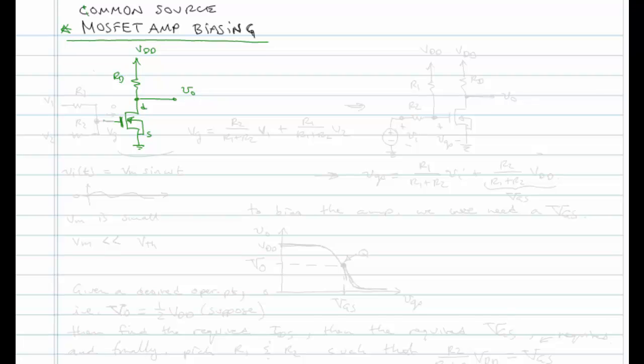So what I want to set up is a scenario where we have an input signal, ultimately an input signal that is going to be a pure AC signal, no DC offset. So let's say it has some magnitude Vm, and it's a sine omega t. Okay, so just a simple sinusoidal signal, but it's centered around 0. So if you apply this signal right to the input of your MOSFET gate, nothing's going to happen because this signal is small.